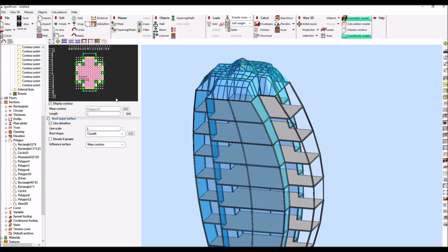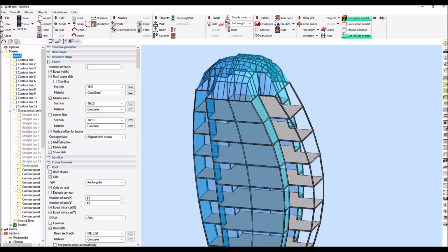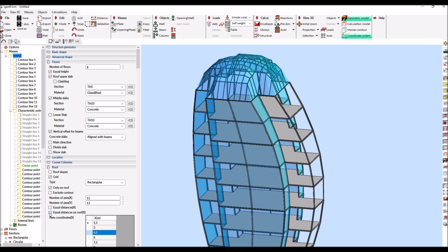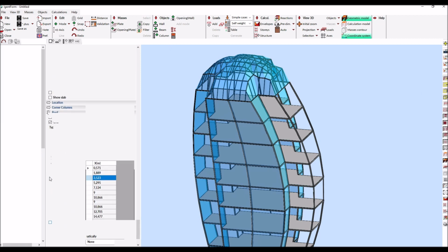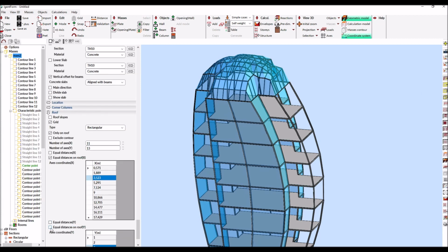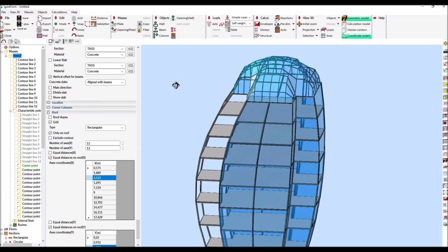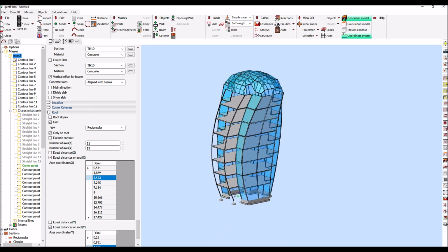Sometimes it is necessary that the distances between the beams are the same, not in the XY projection, but on the roof surface, in order to equalize the dimensions of the roof slabs. This effect can be achieved in the program by disabling the equal spacing option or enabling the equal spacing on the roof option. The program will automatically calculate the axis coordinates. In our example, this functionality was shown for a roof shaped in the form of an ellipse.